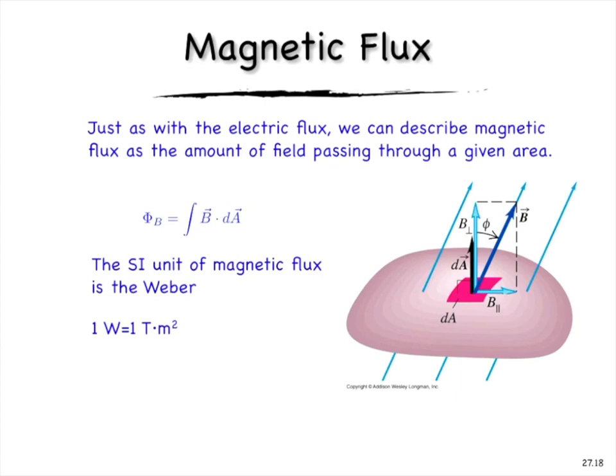But there's a more direct way. Once you know that a coil of wires, a solenoid, has this magnetic field pattern that looks like a bar magnet, then you can use another form of the right-hand rule. Curl your fingers in the direction that the current in the coil flows. In this case, with my right hand, that is like so. And that leaves my thumb pointing in the direction that the field goes inside the core.